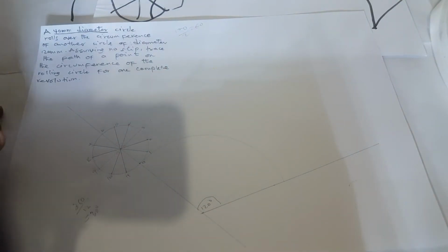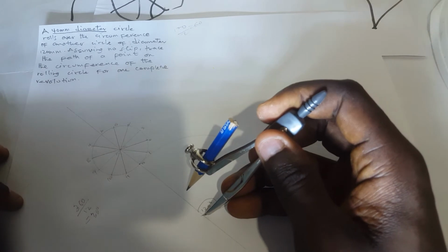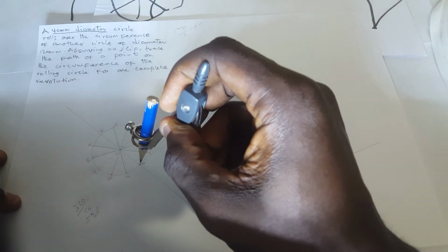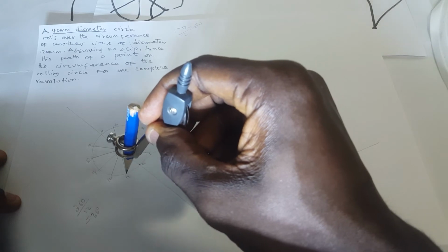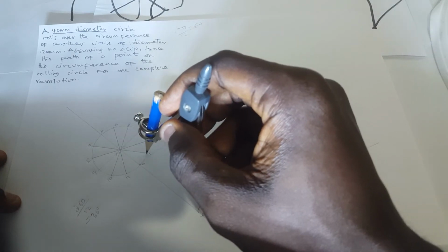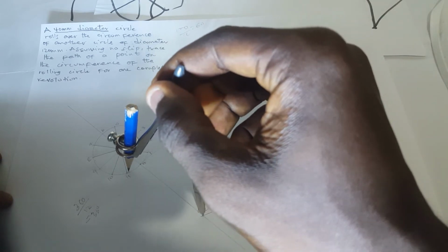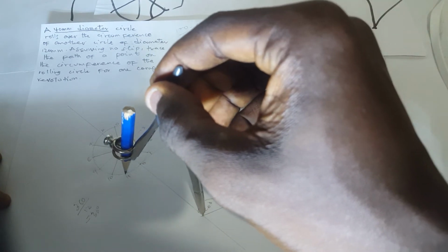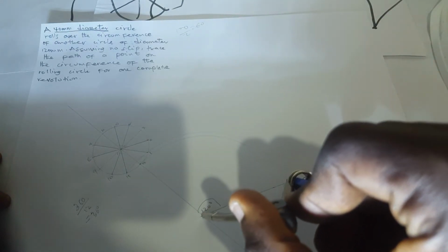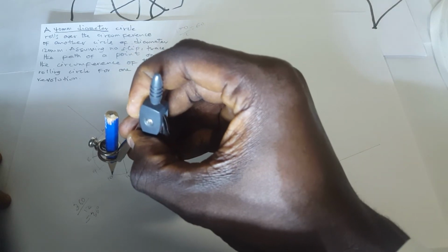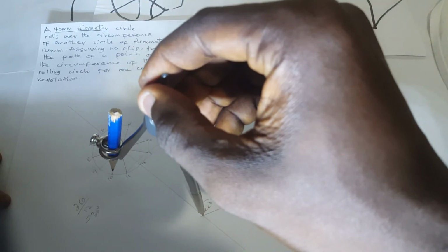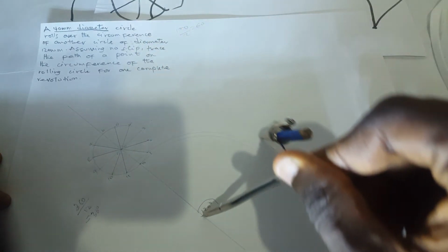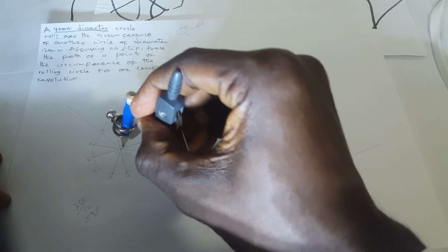Okay, that's good. So now what we have to do is that we take this back. We've already done for the 0. So what we do is that we stand at 11. Okay, we make sure that we draw an arc, but we make sure that this arc is passing through both 11 and 1. Okay, so you start at 11, you draw, but you stop here where the angle 120 degrees ends. You do same for 10, then 2. So you draw. As I said at the beginning of the video, you have to make sure that these lines are all constructional lines, or they are thin lines.